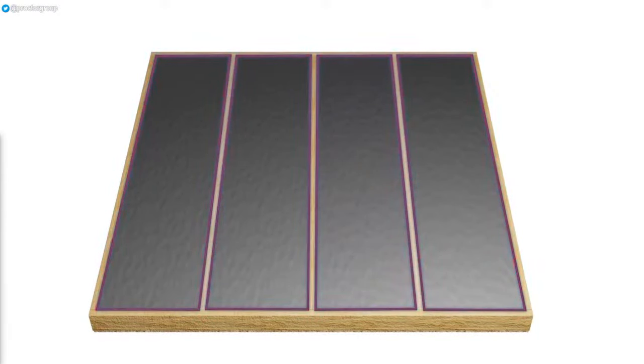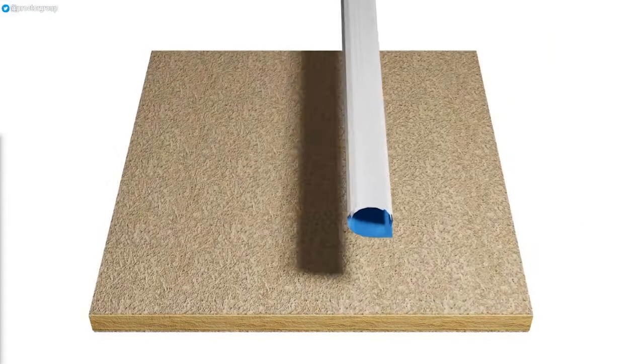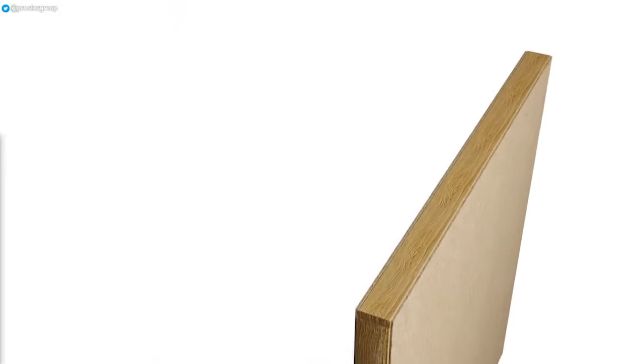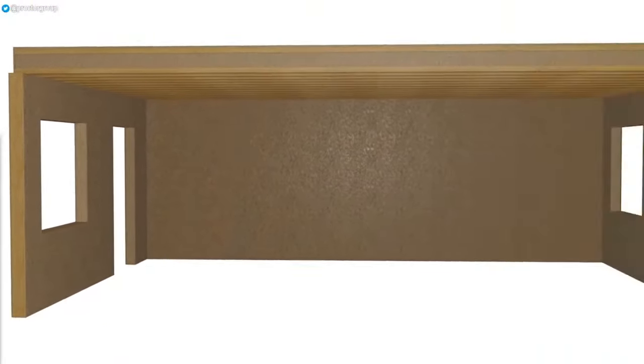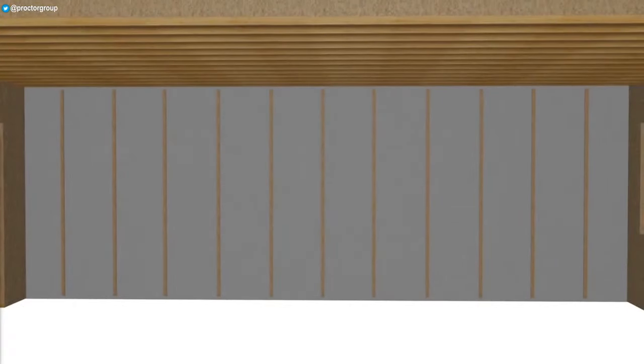Because the insulation is factory fitted in this type of frame, it can be installed to tighter tolerances with less potential for unwanted air movement around the insulation boards. This convection can lead to reduced performance due to higher than anticipated air leakage, or to condensation problems if the vapour tightness of the insulation is being relied upon to provide a vapour control function. These panels are transported and erected on site in the same manner as open panel systems, but services are typically installed using internal batten spaces, which can further bring air tightness benefits.